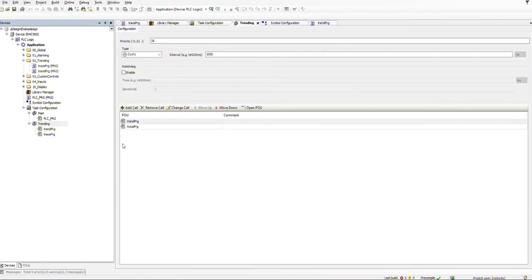In the CODESYS example project, you can also find trend.png, where the code is being executed. In this case, we used random generated values to fill the datasets. Notice also the maximum number of records in the init method. This will tell your trend function block instance what is the maximum number of points. When this number is reached, the database will start removing the oldest records by replacing them with the newest ones. It behaves like a ring buffer.